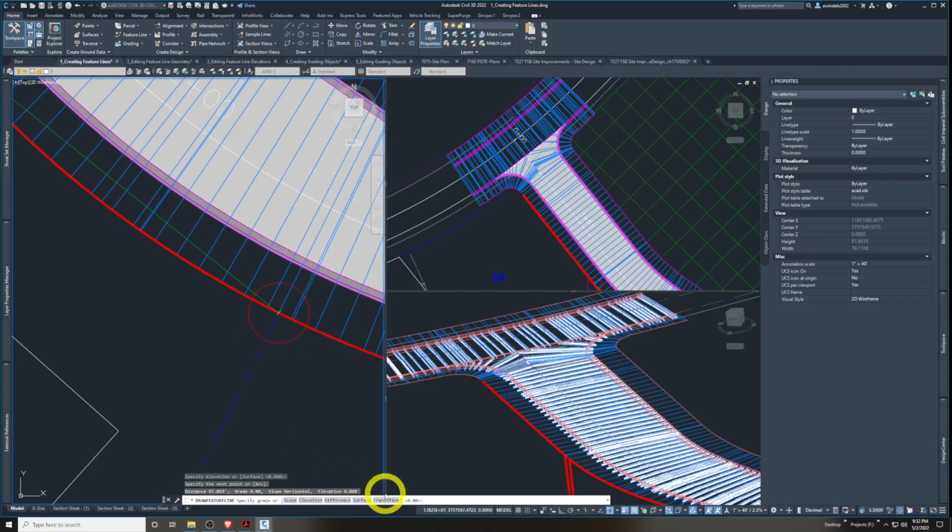Now, in this case, the book wants us to do something I would probably do oftentimes, and we have options. We can say a slope from where we previously came from, the last point, or a specific elevation, or a difference to something we know, an elevation, or a surface. A transition I've never used. That'd be like a transition amount, but it sounds similar to difference. So I'm not sure how this one works, but surface, we'll pick that.